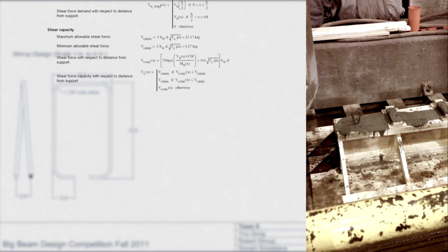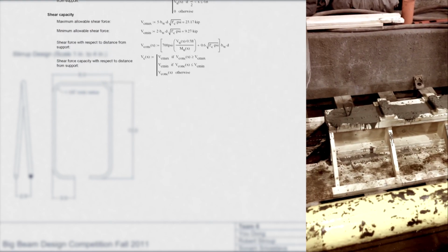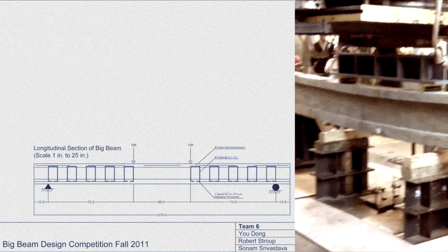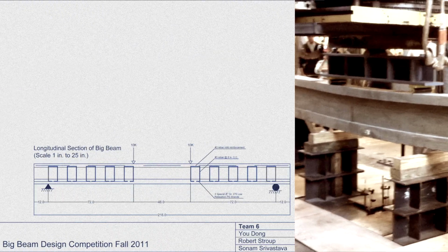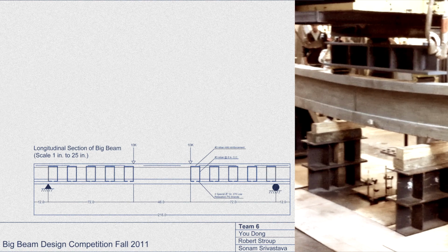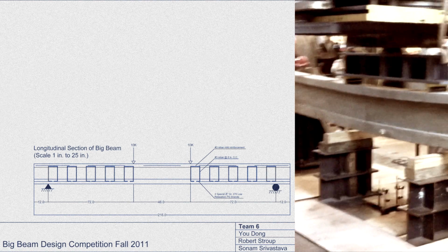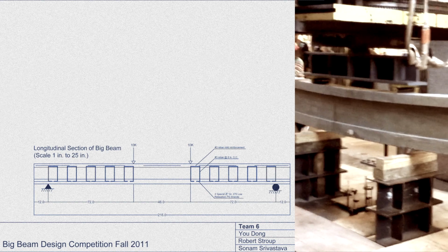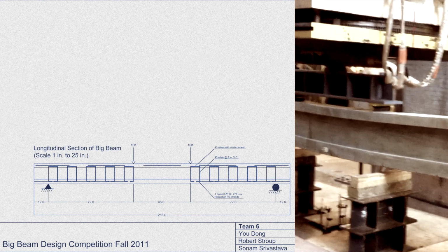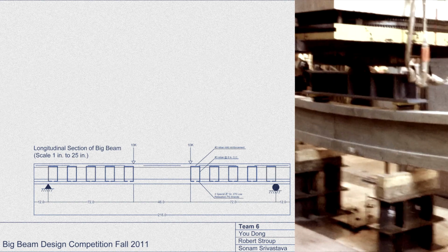This included a two-step process of, 1, first determining the strain due to pre-stressing, and 2, then calculating the strain due to decompression. After these two strain values were found, a stress-strain curve for the pre-stressing strands could then be plotted. Instead of using ACI section 18.3, 3 iterations were then made to determine the force of pre-stressing in the section. In the first iteration, it was assumed the pre-stressing force was exactly 200 KSI.